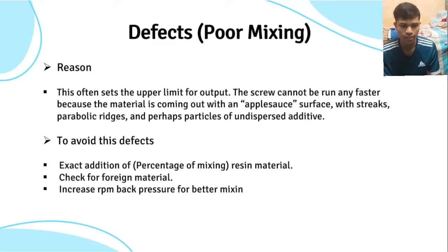Okay, for the high pressure is good for mixing. A valve will do this, or a gear pump pressure control that can serve as a valve. Cooler dies increase the resistance, thus raising the pressure in the system. Finish rings will raise the pressure, but as they keep clogging, the pressure is inconsistent.